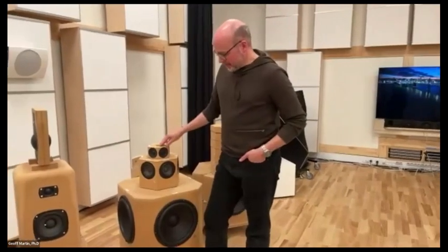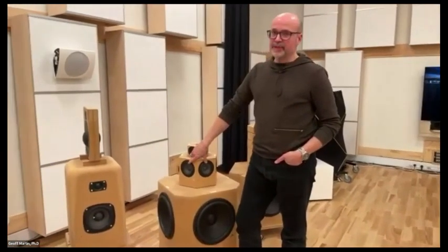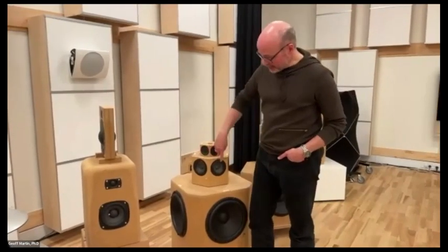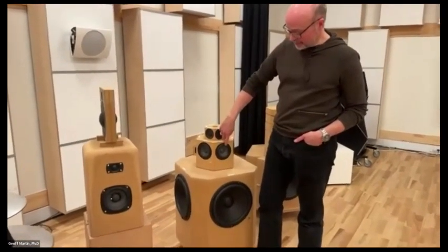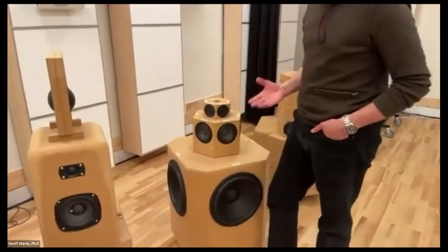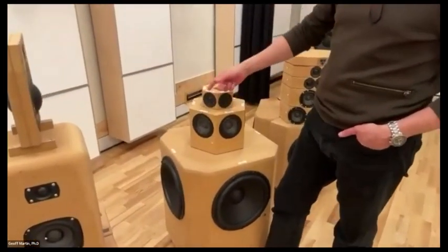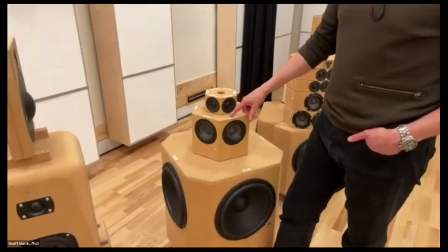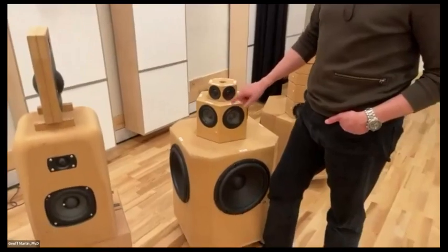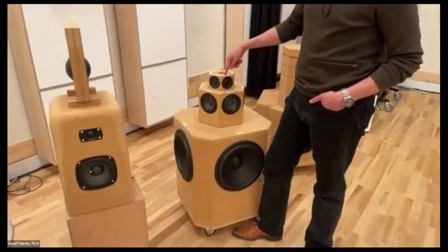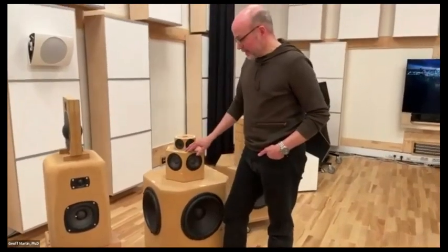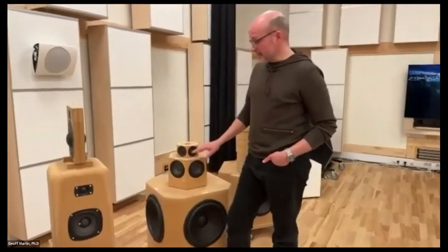The reason being that these drivers are simply too far apart. So we're getting lobing effects. This driver can't be used to control the amplitude of this driver off axis, which was our goal. The whole idea with beamforming is to use interference between the drivers. And unfortunately, because we're using these so high up in frequency before we get to these 1.5-inch tweeters, we can see and hear lobing effects. And that was unavoidable because of the design of the speaker.